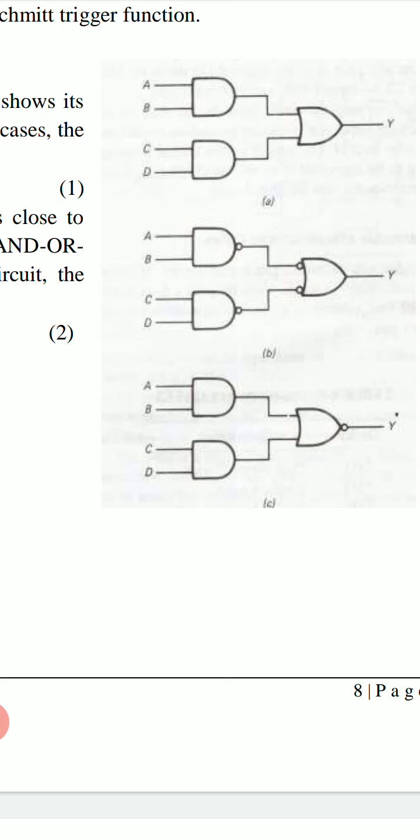Output Y is AB plus CD. Figure B is the same. It also produces Y equal to AB plus CD. There are 4 bubbles formed as shown in this figure.